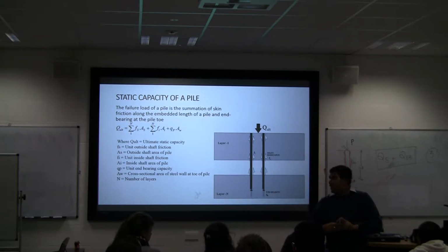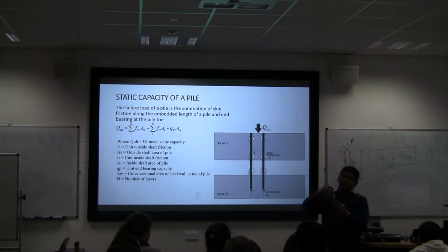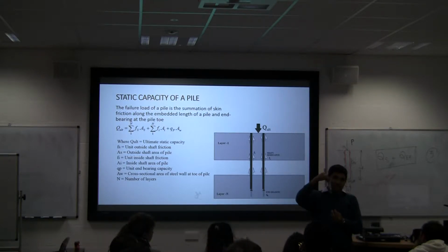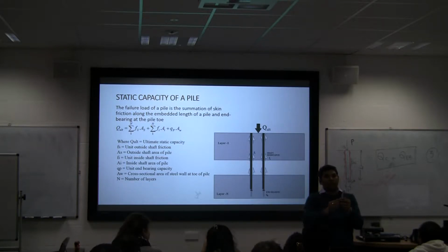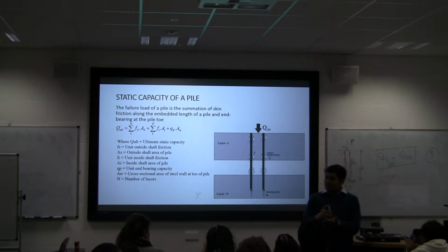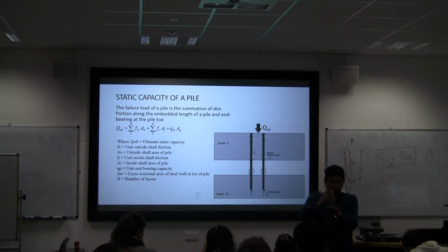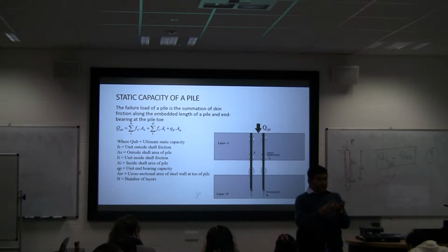Yeah. So, if the pile drives with soil coming inside, that means it is driving unplugged. It's not plugging at the bottom. It's unplugged, isn't it?